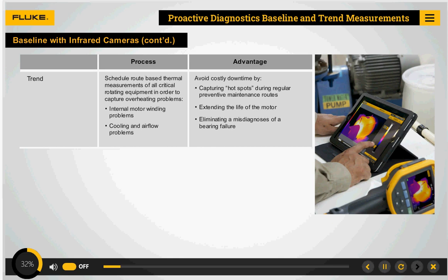A thermal imager is a great tool for spot checks to see if motors and associated panels and controls are operating too hot, and for troubleshooting to track down the specific failed component at fault. It can also check for phase unbalance, bad connections, and abnormal heating on the electrical supply. If a temperature reading in the middle of a motor housing comes up abnormally high, take a thermal image of the motor and find out more precisely where the high temperature is coming from: windings, bearings, or coupling. If a coupling is running warm, it is likely an indicator of misalignment.